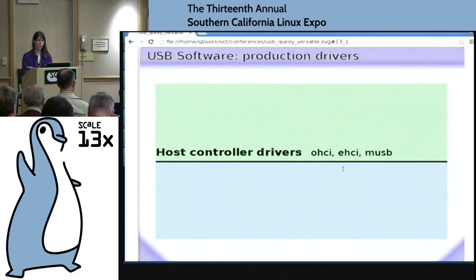because it's one of those IP cores that Mentor Graphics once upon a time designed, and they've licensed out to a whole bunch of different SoC chip makers. There's been a lot of forking going on, so you can't necessarily depend on the things that work with one MUSB to work on the other. In fact, they're some of the ones that were responsible for that annoying non-hub supporting trick. But anyways, if you've got an MUSB, then you'll just have to cope with it. Some of the newer ones actually seem pretty decent.